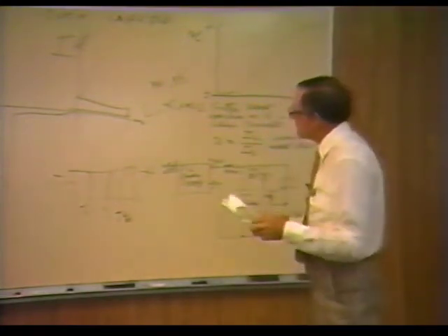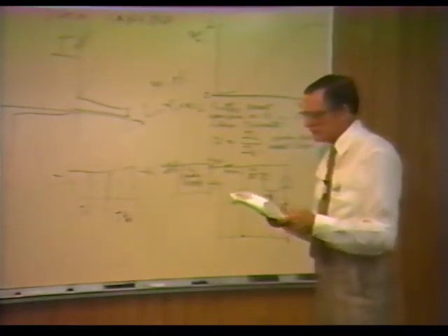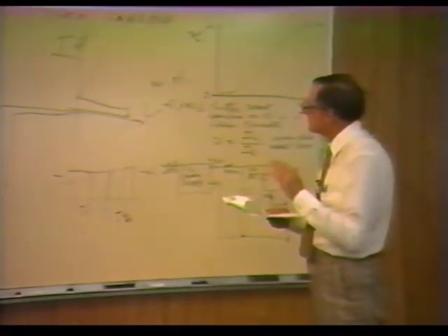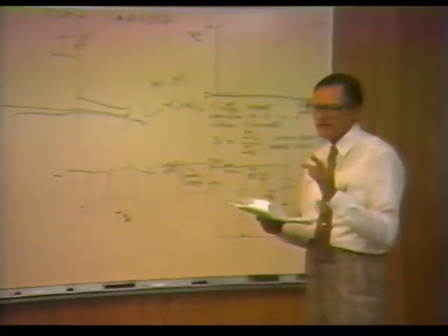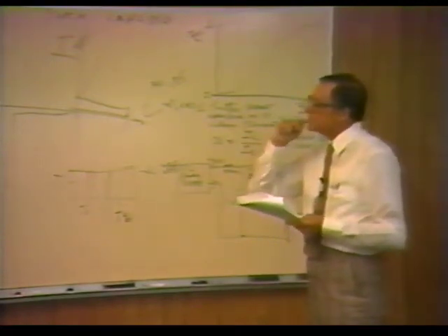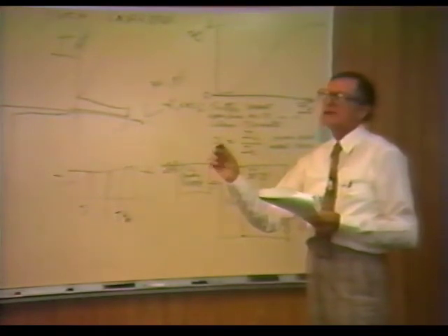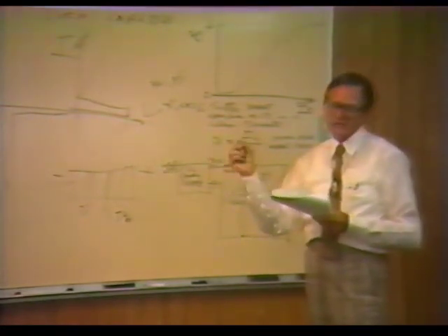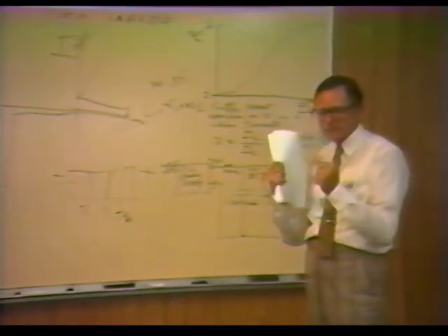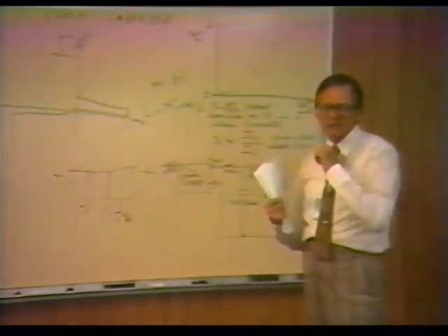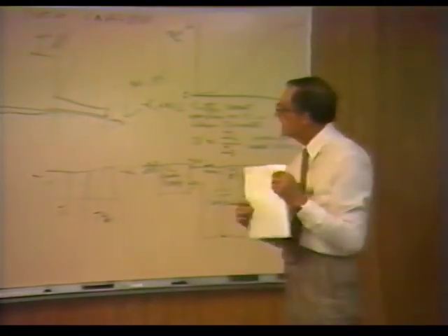Now, the important part is that the turn-on characteristic is essentially the number of carriers that pass the junction area. So if you shine a light on there like a flashlight and it isn't very bright, it has very few carriers moving through. The SCR will not turn on. If you hit it with a xenon flash, the very bright light produces a lot of activity and it will turn on. I don't have time to talk about the turn-on mechanisms we have.